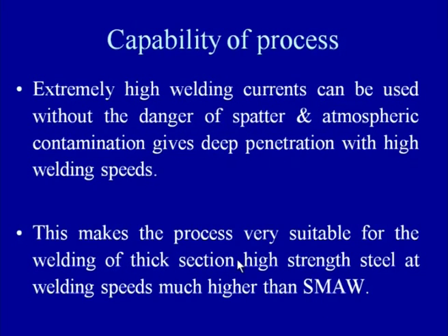So, the ability of this SAW process to work with higher current provides deeper penetration and higher welding speed, a spatter-free weld, and the reduced contamination of the weld from the atmosphere makes it very good for welding heavy sections of high strength steel.